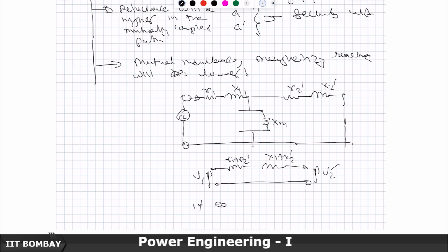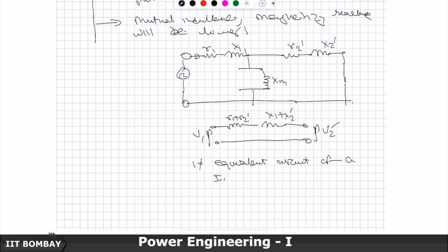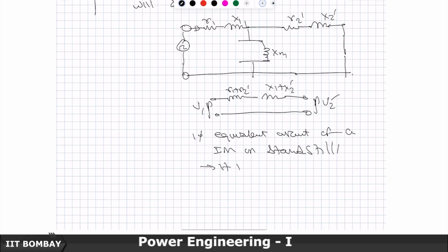And this you could say is the single phase equivalent circuit of an induction motor at standstill, and it is worrisome, it is bothersome because of the short circuited rotor winding. So, large currents will flow; you expect large currents to be drawn from the supply.